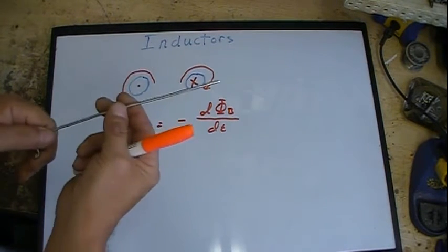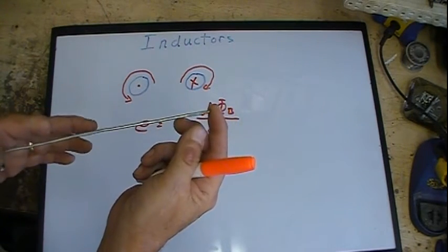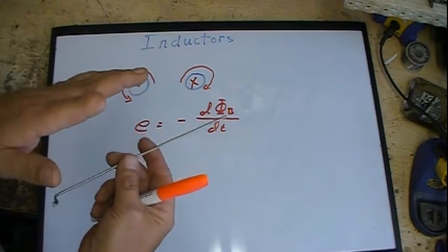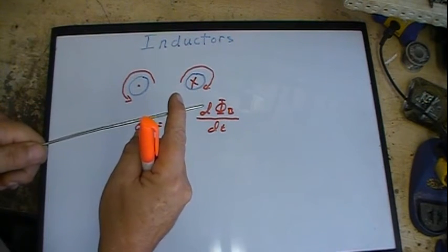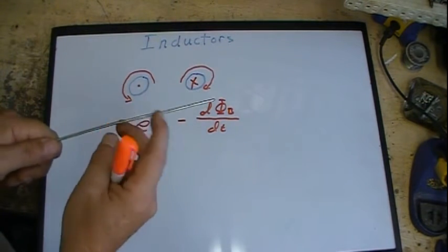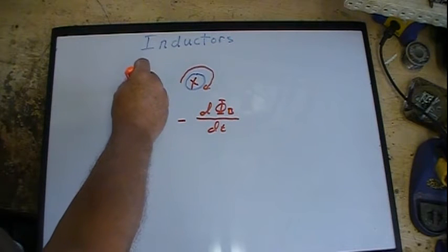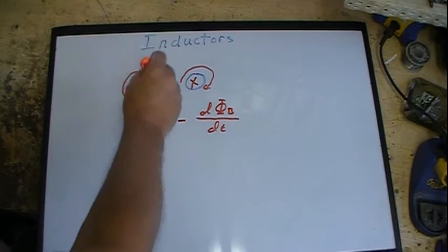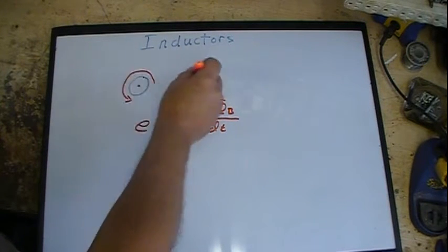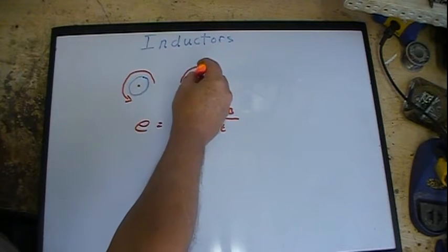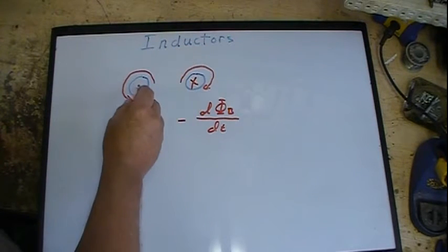Basically, if my magnetic field is being produced from another wire that I put voltage on, when I move the second wire in that field, the actual direction of current will be in reverse to the initial wire. So if I had, say, this wire hooked to a battery, and it builds a magnetic field, but then I move this wire, or either one of the two, as long as I'm changing that magnetic field or moving a wire through that magnetic field, the voltage will be in reverse. That's what the negative means. It'll be in the opposite direction, just basically what it's showing here.